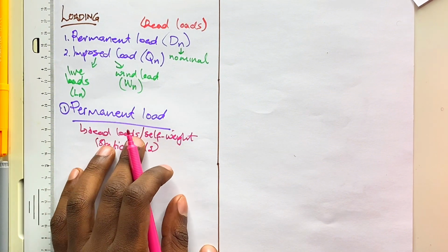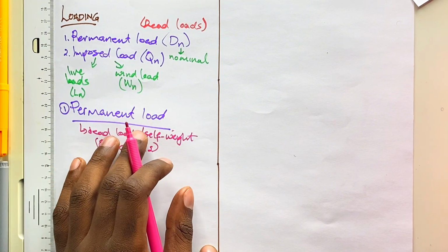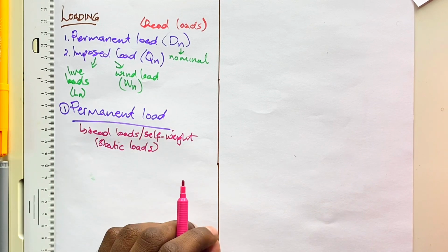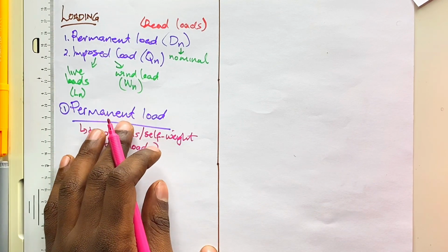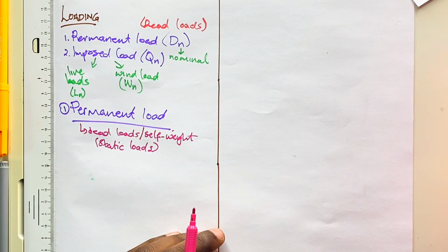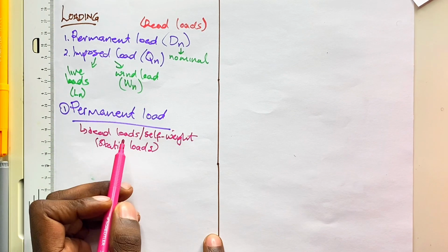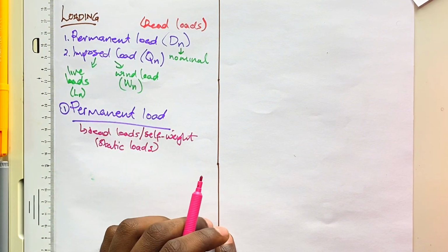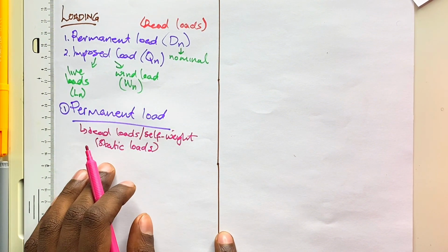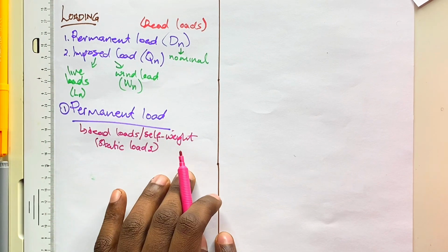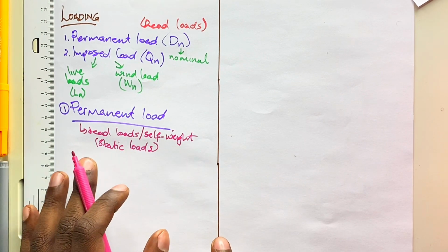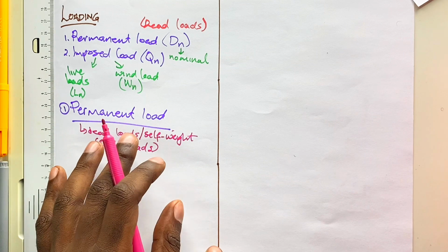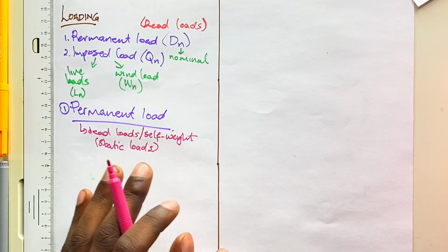These permanent loads are the inherent and constant weights of the structural elements and materials that comprise a building or a structure. So they are part of the structure itself. These loads encompass the weight of everything that remains stationary within the structure, from walls, floors, roofs, and columns. Even the finishes in the structure, such as plaster, the paint, or even the building's own self-weight.